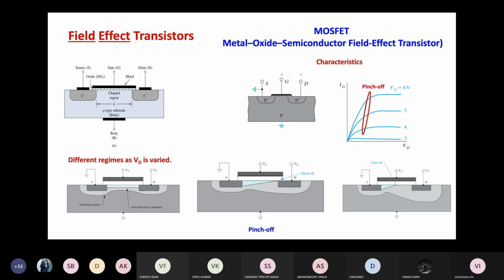Okay, and this is n-type material. If we apply a positive voltage on n-type material, it is a reverse bias situation and the depletion width is increased. And because of the depletion width, the electrons that are coming from the source side are now quickly swept by the electric field of this depletion region to the drain side.